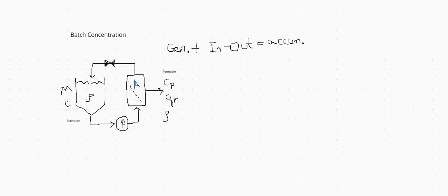One thing that helps is, when you draw your diagram, you can essentially draw a boundary around your system. It's been so long, I'm forgetting exactly what it's called. This helps us figure out what's going on. So we can see that there are no streams into the system, but there is a stream out, the permeate. And then we can go over to our general mass balance equation.